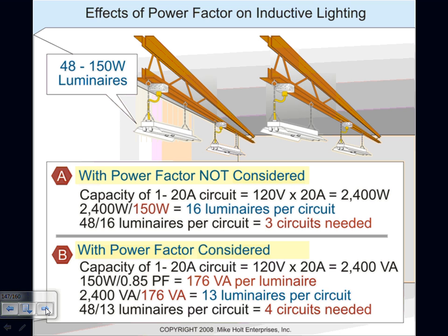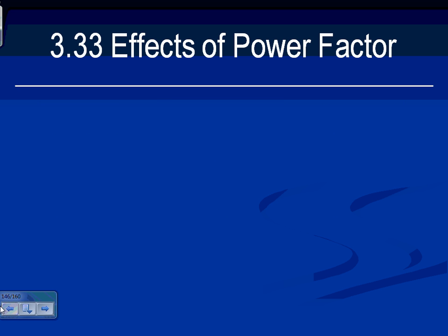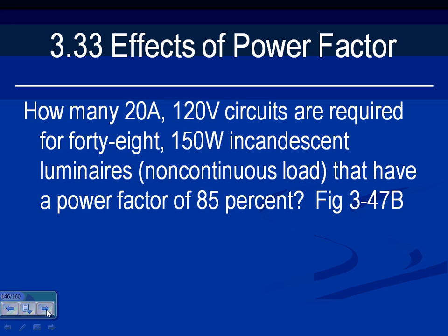Why would an incandescent light have a power factor of 85%? Did they say incandescent power factor? Go back one step. Fluorescent, non-continuous luminaires, incandescent power factors. Oh, I'm sorry. Okay, how many 20 amp 120 volt circuits are required for 48 100 watt incandescent?